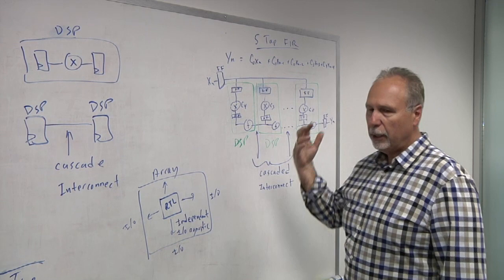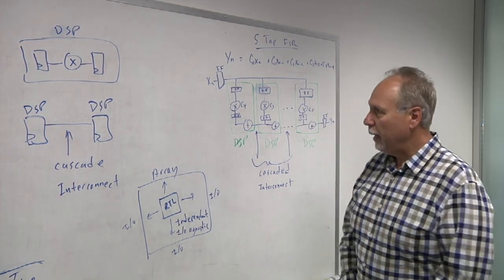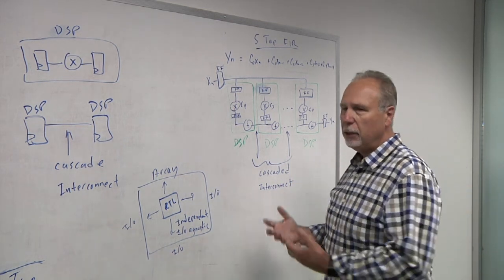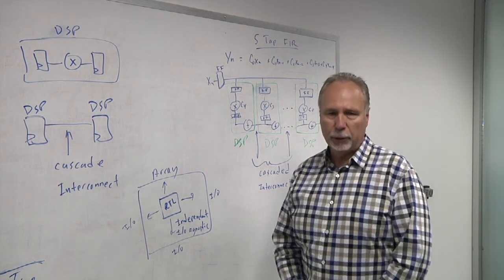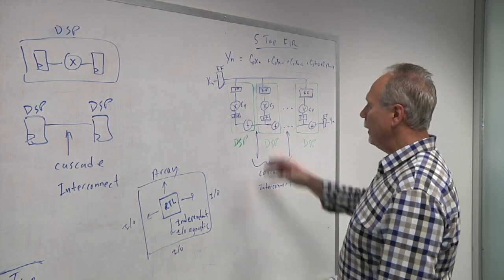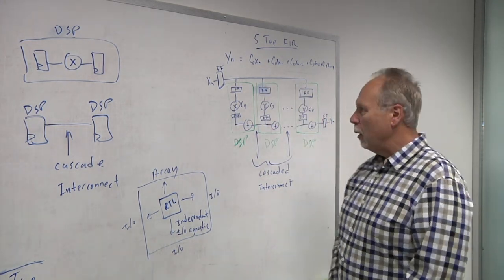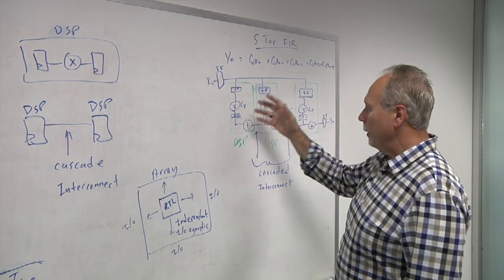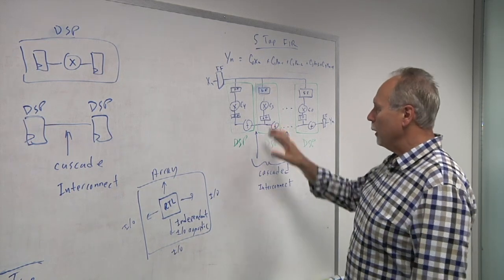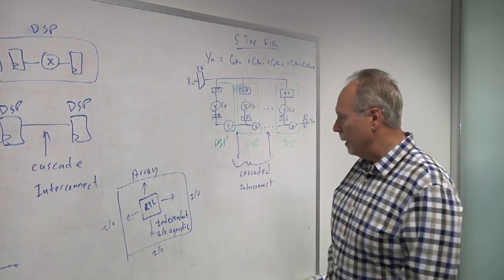This FIR filter actually uses multiplies and additions, and if you map that into an FPGA with DSPs that have multipliers and adders as DSP elements, or MACs, the different elements that will impact the performance are either inside the DSP or between the DSP elements. So for instance, a 5-tap FIR filter uses 5 MACs or DSPs, multipliers and adders.